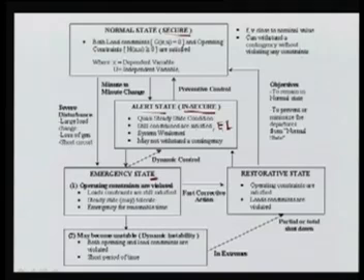In the emergency, there are two types of emergency he has classified, that is, your operating constraints are violated, means your load constraints are still satisfied. The steady state may tolerate the emergency for a reasonable time, so we require fast corrective action, and then we can come into the restorative state, and from the restorative state we can come back to the normal state.